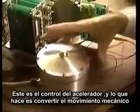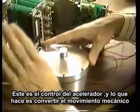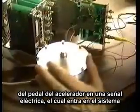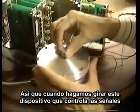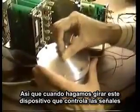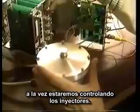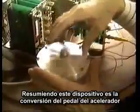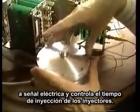This is the accelerator control, and what it does is convert the mechanical movement of the gas pedal to an electrical signal, which is brought into the system here and controls the injection. So as you turn this device, which controls the signals, you'll notice that it also controls the injectors as the same function. This device right here is the conversion between the gas pedal and an electrical signal which controls the inject time of the injectors.